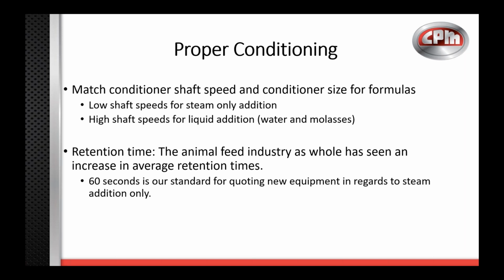Now, the reason we want to use a high-speed shaft for those liquids, to give you an analogy, one that was given to me that I've always liked, is when you're mixing paint or different colors of paint or paint thinner with a paint, the faster you mix it, the better it does at distributing that paint all together and evenly, making it what you need it to be. And so that's kind of the same point of view, the purpose behind it. Also with steam, it's already been atomized, so it mixes easier anyway, so we don't need that extra speed to go along with it.